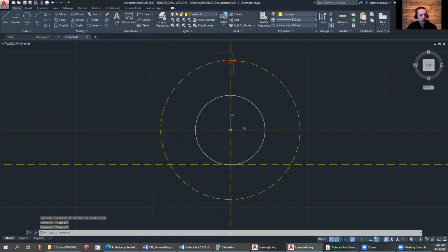All right, so what you're going to notice now is between this circle and this line, we've got some intersection points, and that's where we're going to lay out our other circles. So I'm going to turn my grid snap off. And then looking at the drawing, I've got 3 circles at 0.56. And in the drawing, you're going to see some dimensions that say, 0.56 times 3.